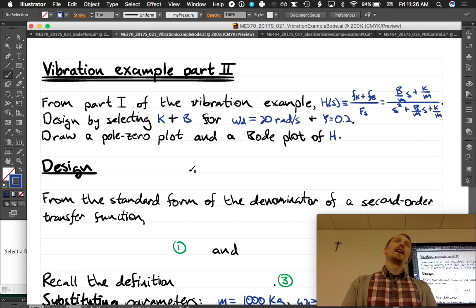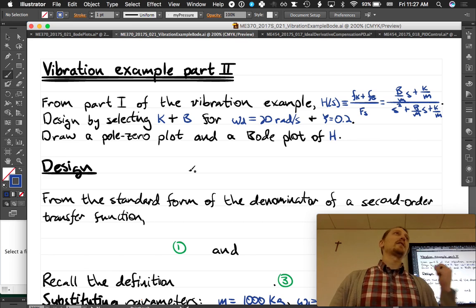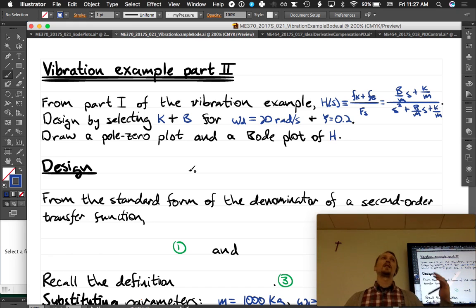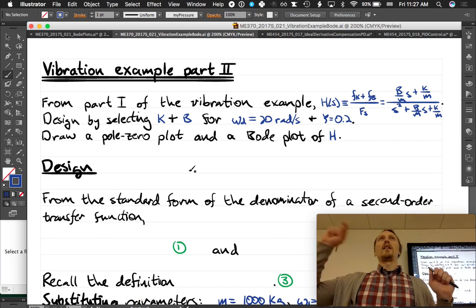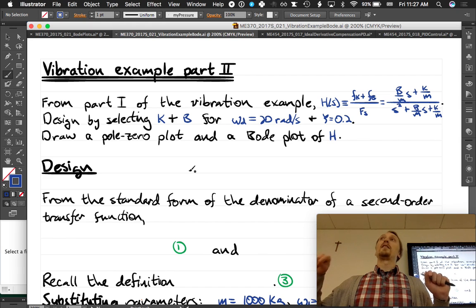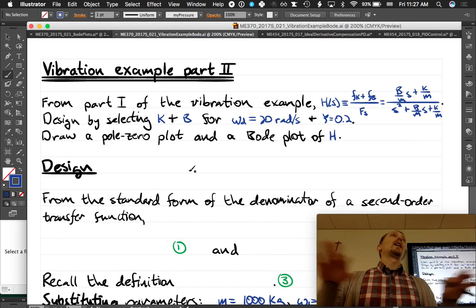We don't want that. We saw those Bode plots for second order systems that have those resonances at the natural frequency, right? We don't want to be at that natural frequency, because how is the output amplitude related to the input amplitude on or near resonance? Is it greater or less than the input? Greater than the input amplitude. So we don't want to operate there.